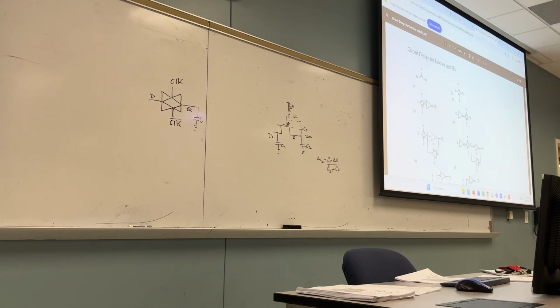Can you tell me what does inverted latch mean? Only Q bar. Inverted latch means you have only access to Q bar, which is the opposite of the actual Q. So if you look at the Q bar and you see Q bar is equal to 1, that tells you the flip-flop or the latch is holding a 0. Did you get it or not? This is called the inverting latch. Clear? Okay.